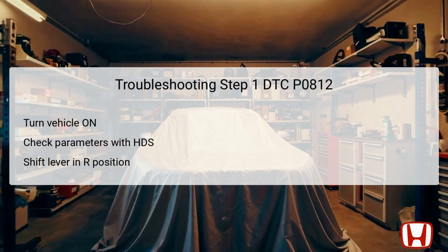It's essential to observe the current conditions displayed by the HDS with this setup. If the current conditions match the threshold values, it may indicate an intermittent failure, meaning the system appears operational at that moment, despite previous faults. If the parameters do not match, however, this signifies that the failure is currently duplicated, necessitating further examination.